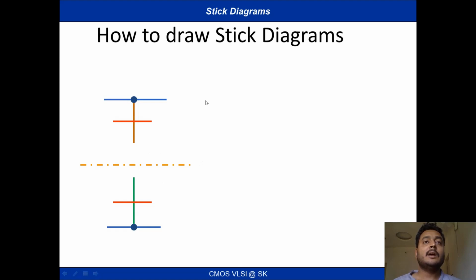So the next thing is we're going to connect this one, and you can see I'm using a metal line. This is blue, because we understood that only two layers can cross this demarcation line: one is the polysilicon line, and the other is the metal layer. Okay, the substrates, these two things cannot cross each other. That's why I'm using a metal layer here. On this metal I'm going to indicate the contact, because these two are different layers. And next we go for the polysilicon connections. Okay, so this is how your stick diagram looks for a CMOS inverter.